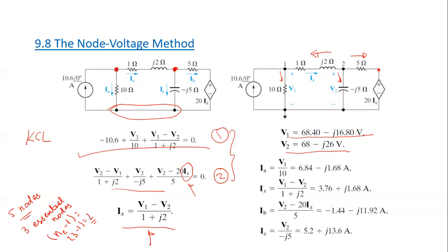So as you see, we use the same rules and the same methodology that we used to solve the circuit with resistances using the node voltage method. The only difference here is that you will have complex numbers as the coefficients. So you need to look at each branch. Here we have only one component, here we have one, here we have one, while here we have two, okay?